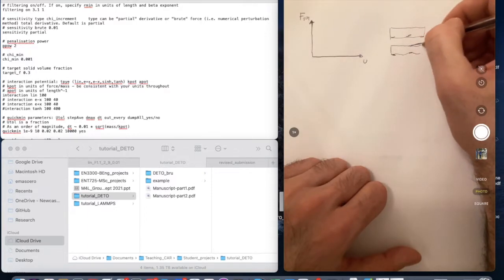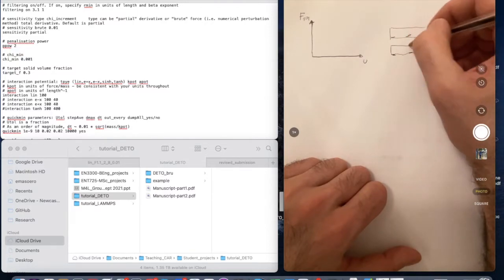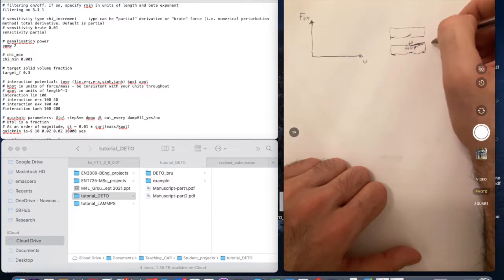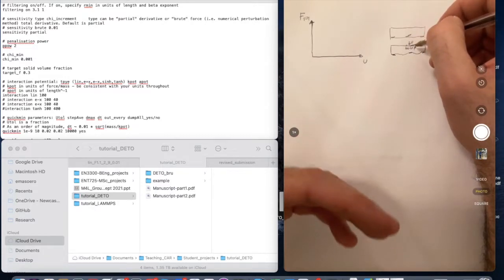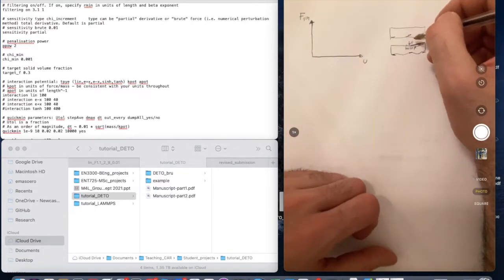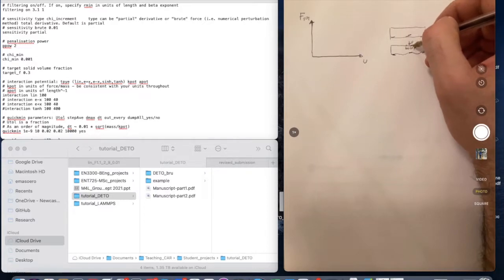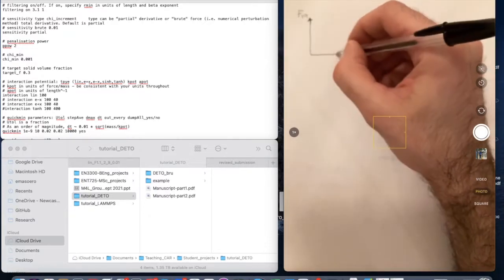This should be straight, while going up a bit. So the 3 supports are blocked, but because you are pushing the top down by a quantity U, you are going to need a force F on these particles, and the beam will progressively deflect. The simulation will keep increasing the imposed displacement U until obtaining the target imposed U of 0.4 millimeters.